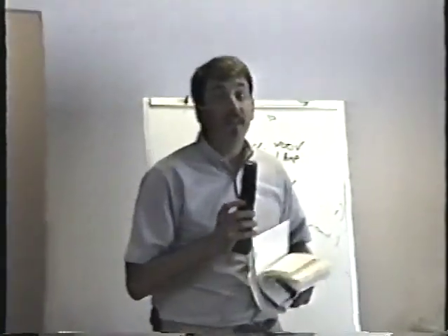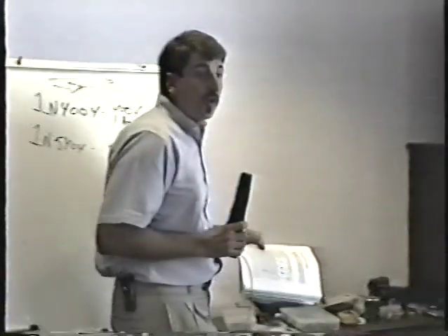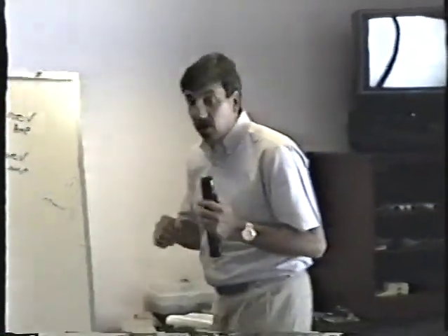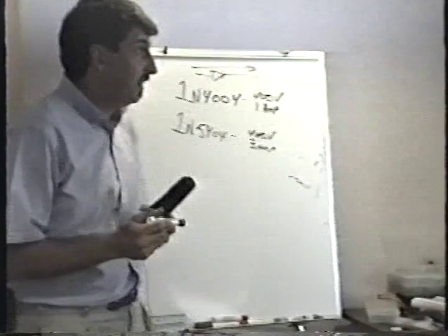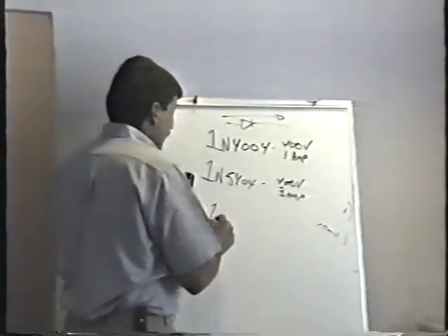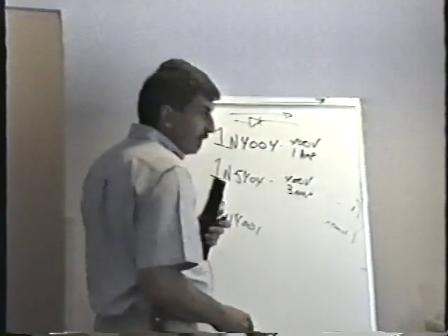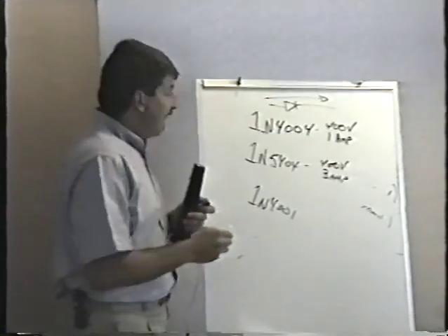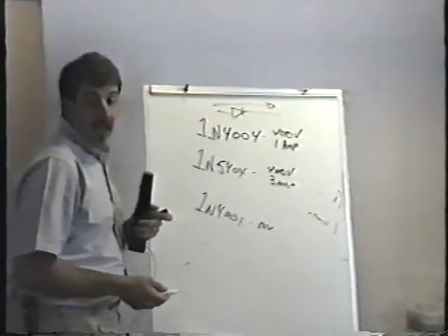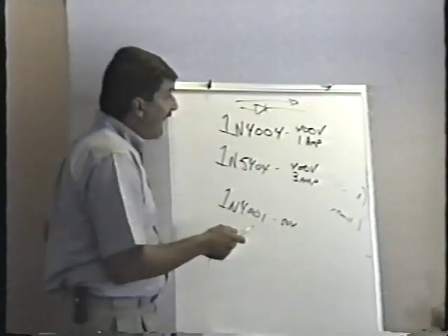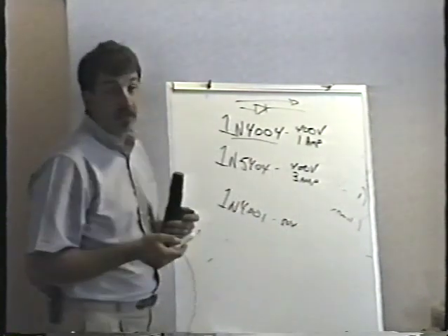Well, here's the really cool thing about diodes. When you're working with diodes, if you need to substitute a diode, you can always use another diode of the same or higher voltage, the same or higher current. You can always go up in voltage rating. You can always go up in current rating. For example, another common diode that you might see in many different places is a 1N4001. What's the voltage rating of that guy? That's only a 50 volt diode, isn't it? If I have a 1N4001 and it's bad, I can use a 1N4004 as a substitution.